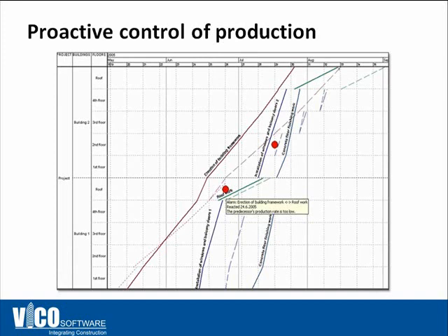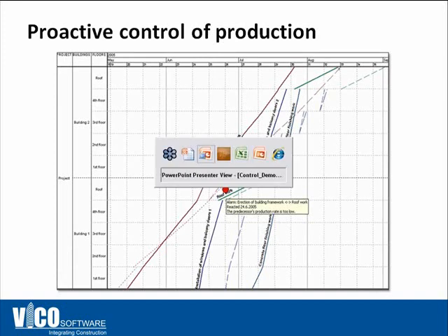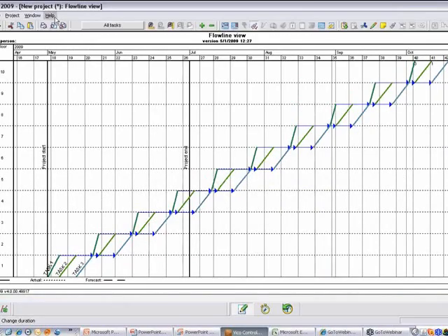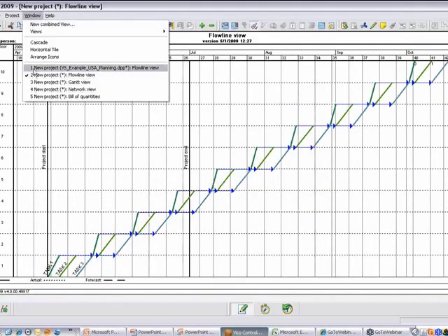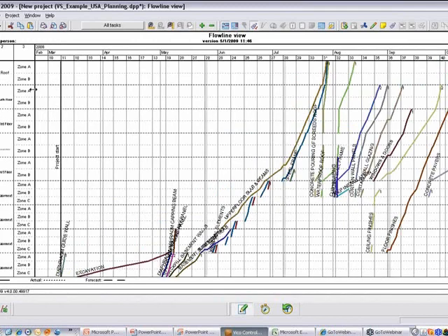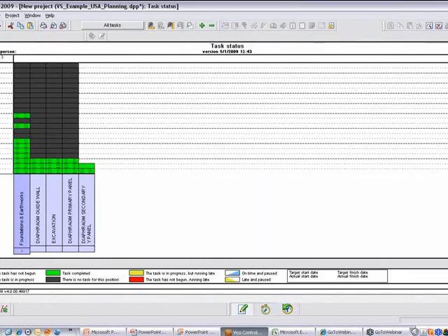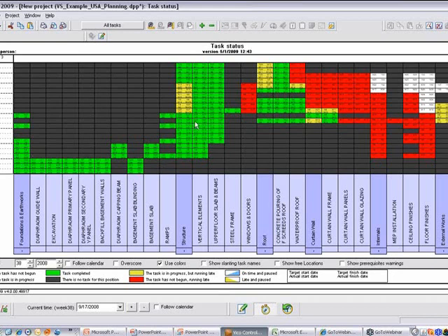For litigation purposes, every single delay can be logged in the same environment, and it can be retrieved and printed out later. So if you look at this inside control, I'm just going to open up an example project. You can see that if I switch to my control chart and I switch to planning mode, some activities have been completed, some of them are delayed, and we've been pretty much lagging behind on this project. You can see that all the finished activities are red.